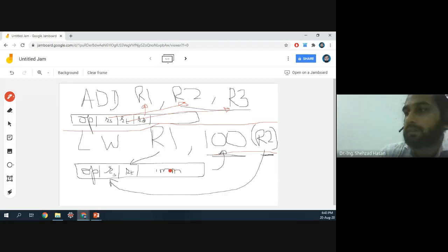So what I wanted to say was in a load instruction, there are no 2 source registers, but since in the decode stage we have to read the registers irrespective of what instruction it is, and since these are the 2 fields for the source register, we are going to read both of them in any instruction. So in any instruction which is in the decode stage, you are going to take these 2 register codes and give those register codes to the register file, and you're going to read 2 values. If you need that value, you're going to take that to the next stage. If you don't need that value, in the next stage you are not going to use that.